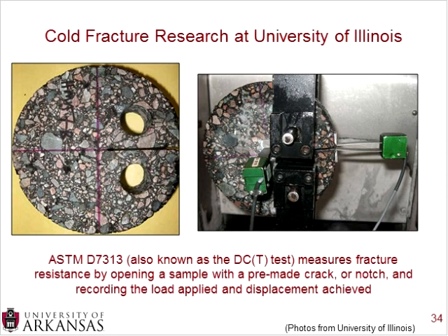So getting a little more into the hard research side of things, one of the concerns of Warm Mix Asphalt is because if you're using these lower temperatures, is it more susceptible to cracking? Well, the University of Illinois has developed a fracture test. This is the Disc-Shaped Compact Tension Test, or DCT test, and you can measure fracture resistance of asphalt mixtures.